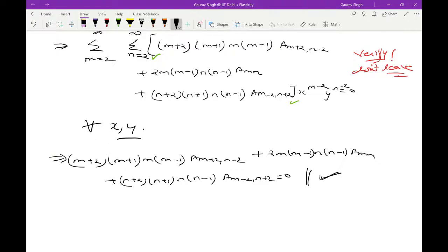So one of the things is that because you have taken your phi to be a polynomial, the stress may also turn out to be of a certain form, and hence it may not satisfy just about any boundary condition. How do you get around this problem? Using Saint Venant's principle. You slightly modify the boundary conditions, okay, so that it fits your taking phi as a polynomial.